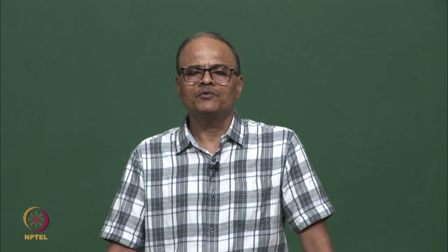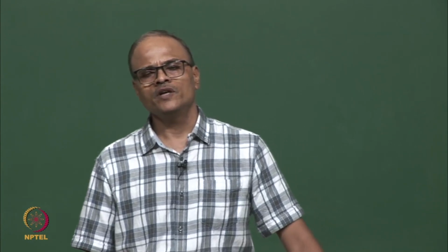So, in this way we come to the end of this lecture. In today's lecture we looked at the modal parameter estimation using the rational fraction polynomial method, which is a multi-degree of freedom curve fitting method. We also talked about how to account for residuals and what is the global RFP.